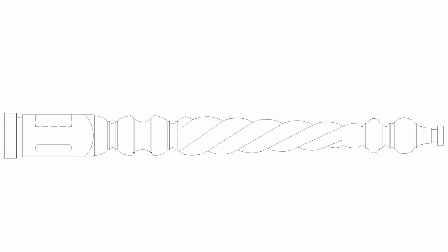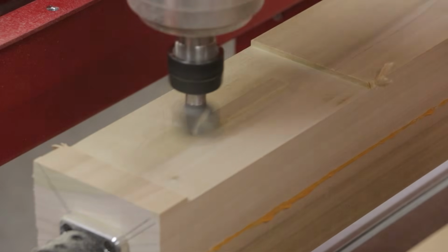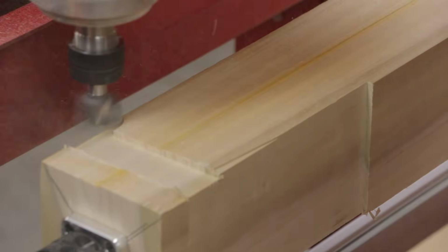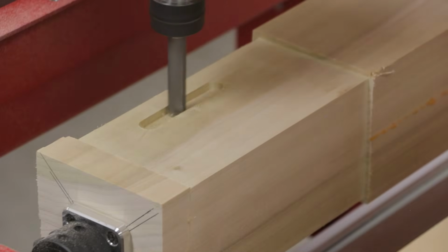Next, we have indexing. These toolpaths are created in this section. These toolpaths hold the spindle in place while cutting and can reposition the spindle to any number of degrees for the next machining process.